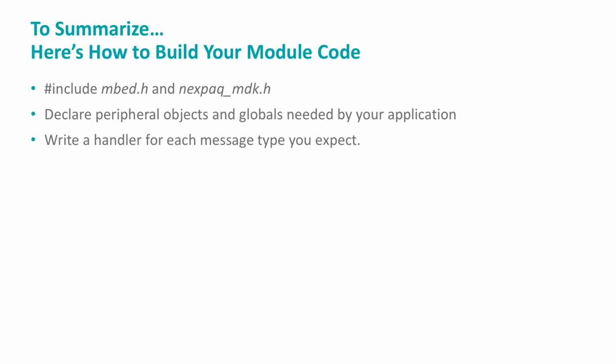In our example, the commands received from the smartphone configured port pins or changed the LED settings. Your application will probably be different, but the overall structure will be the same. Create a constant array that contains the message IDs and a pointer to each of the functions that will be handling the incoming messages. And now you're ready to write the main function.